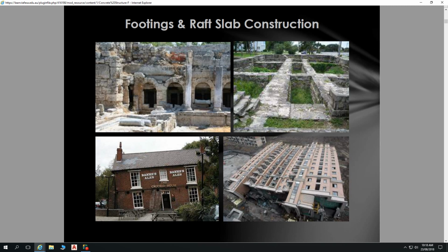Sealicrete. In that application it's like a bit of membrane that impregnates the concrete. It's not just one that sits on top, but actually becomes part of it. You've got both positive side and negative side membranes. If moisture travels from here through to there, a membrane on this side is a positive side membrane, and on this side a negative side membrane.